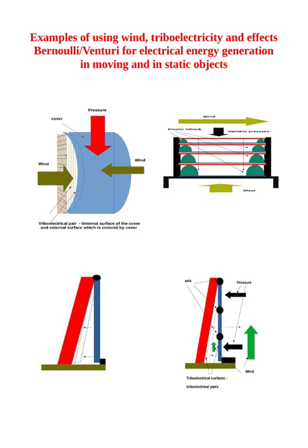There is an example of using several layers of pairs of triboelectric materials separated by elastic separators of varying degrees of elasticity to carry out triboelectric interaction at different wind speeds. Several pairs of layers of triboelectric materials, each pair is separated by elastic materials of different degrees of elasticity, such as springs or polyurethane foam of different thickness.